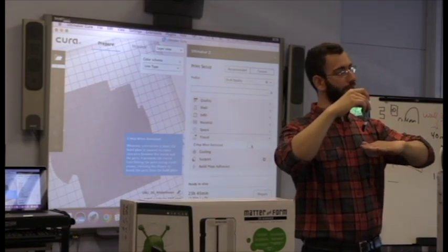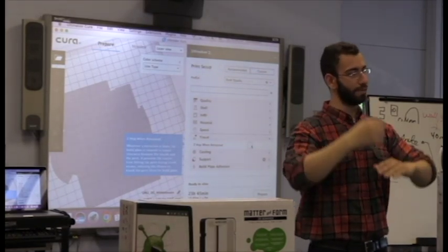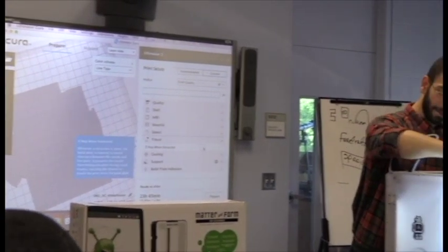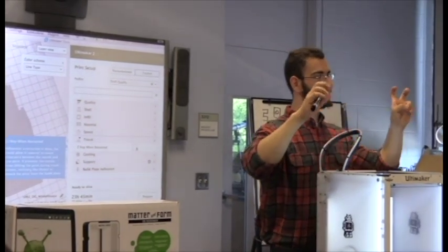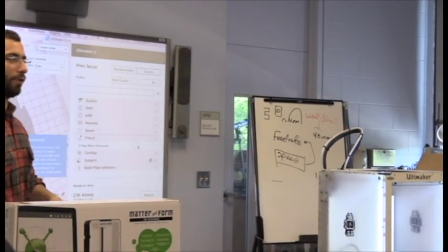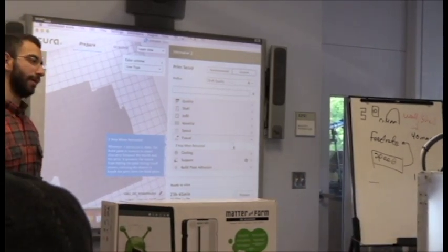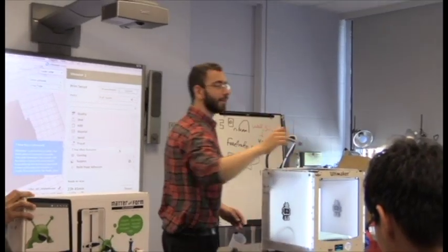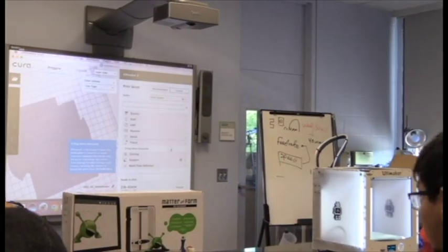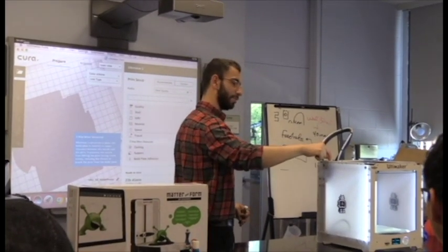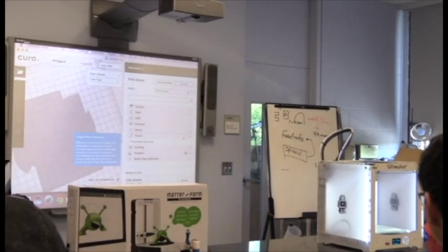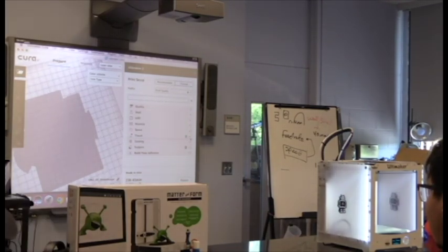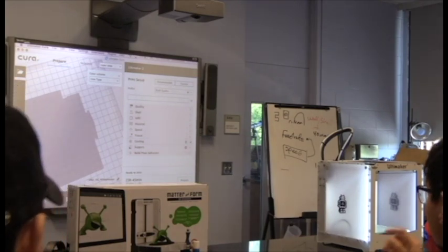What this does is just kind of pulls down the whole thing, pulls down the bed so it's away from this. This already includes, like at the end of the G-code, which I'm going to explain what G-code is in a second, it just automatically goes home to its 0, 0, 0 position. Okay, home is whenever all axes are 0. Actually, home in this instance, I think would be one of the back corner left, something like that. It depends. Different machines have different zeros. Okay, this guy goes all the way up to here. So I guess in this machine, this would be the 0. So I guess you could check that. It wouldn't hurt. So at the end, it'll go back up. It'll increase some distance.